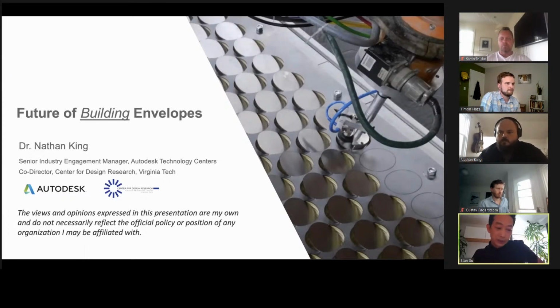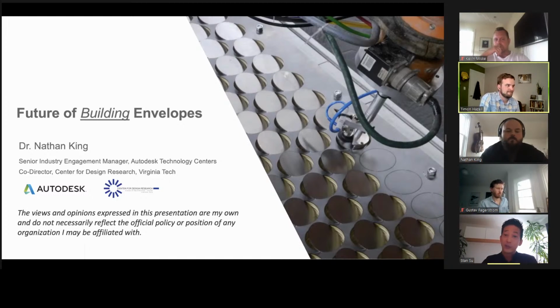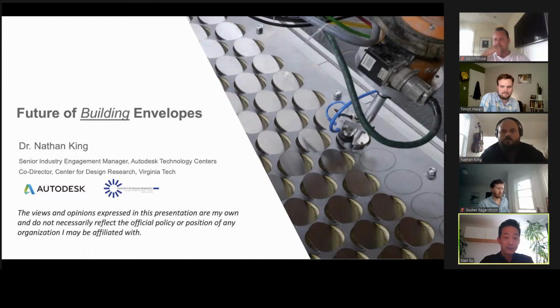Yeah, absolutely. So the initial design was all waterline joints, horizontal. Of course, with all the different geometry, this increased even more types of joints. So really, you couldn't do any kind of post-processing. The most efficient way that they can produce panels for architectural cladding is typically extrusion. So it's really focusing in on extrusion processes, molds, and it really is a tricky thing.